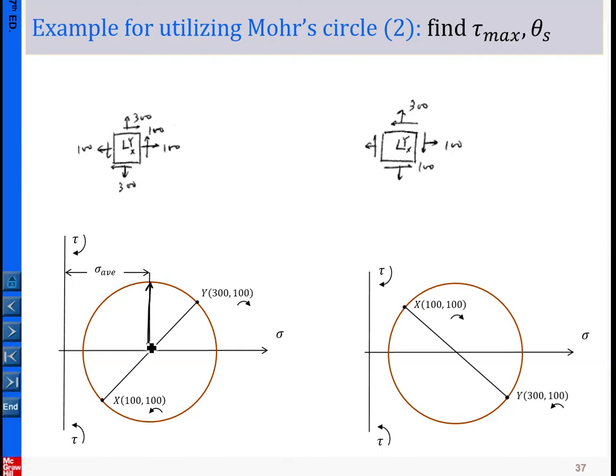This is our maximum shear stress, because that is labeled where the value of the y coordinate is a maximum. Basically here, the north pole and south pole constitute the point of interest on the Mohr circle we want to transform. So let me connect this north pole to the south pole to form a diameter to which we want to transform here.